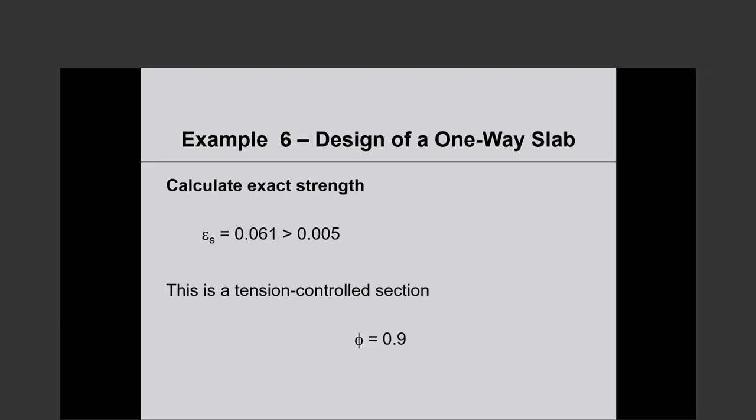No, read that one more time. Section 6.3.2.4.1 of BNBC 2020, there is a coefficient for flat plate slab, that is 0.25 Ig. What should be this coefficient for beam slab?